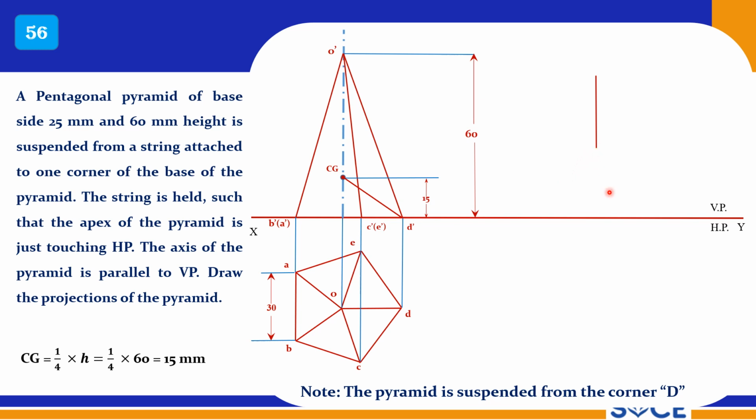So that is nothing but this distance, right, that distance. And now this is CG, and from D you can measure the O distance and cut an arc. Now you can draw this line through CG and apex, measure this distance and cut an arc, or you can set the drafter at 90 degrees and draw this line. Now you can connect it.